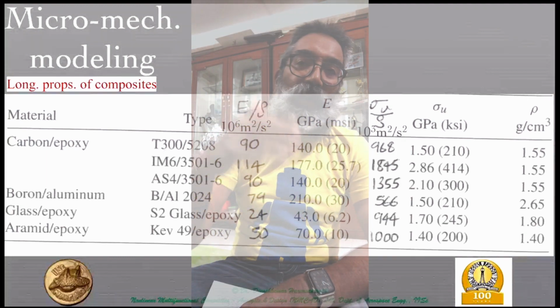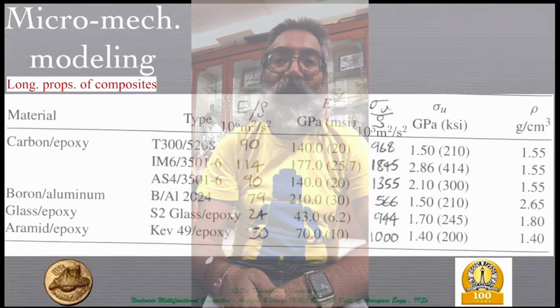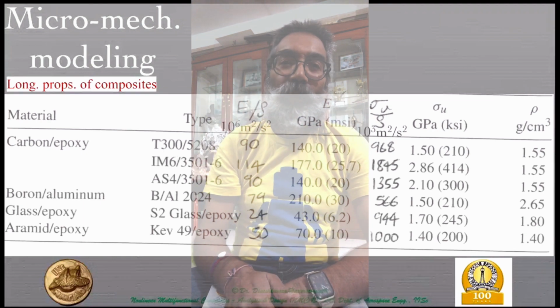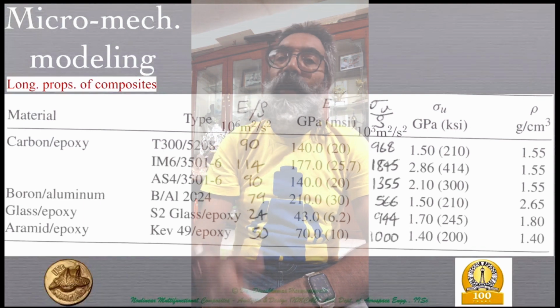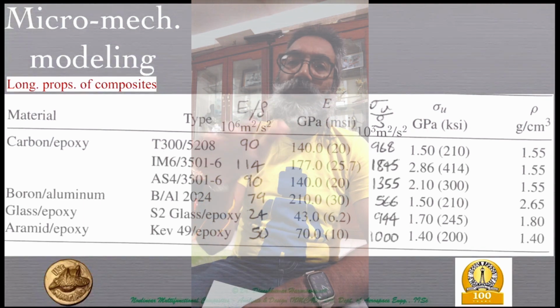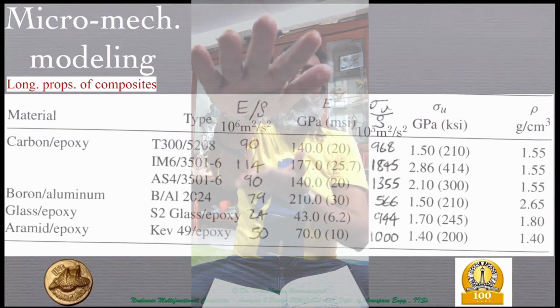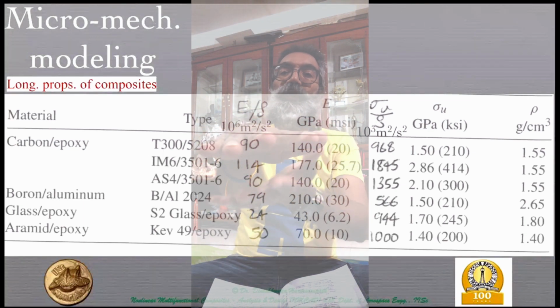The self weight of the wing is much smaller compared to that, n times L, that is load factor n times the lift. And therefore, that is the dominant load that is there. Of course, there's a drag, the pitching moment, etc., and the weights of the engine that is overhung, etc. But nonetheless, most of the bottom skin of the wing is undergoing tension, which is changing with the phase of the flight, and which means fatigue.